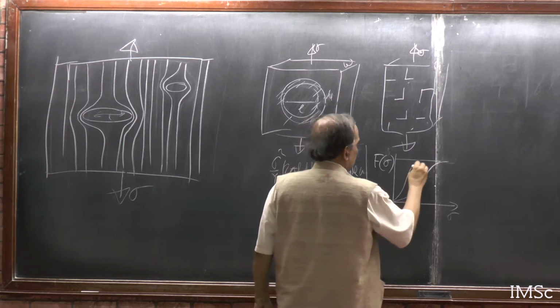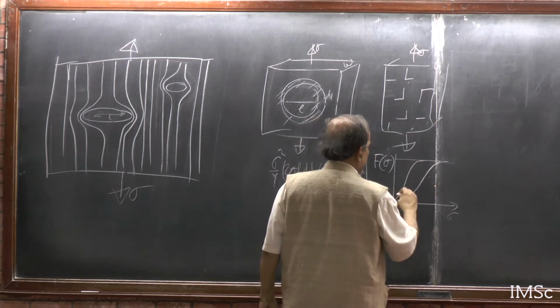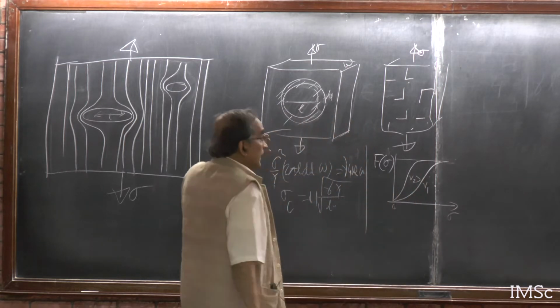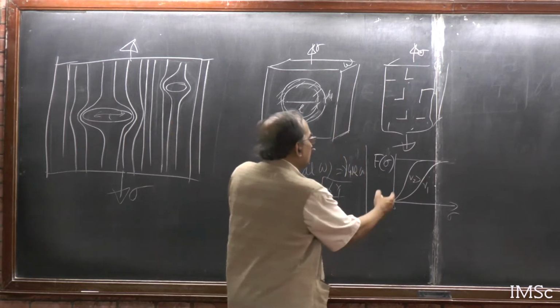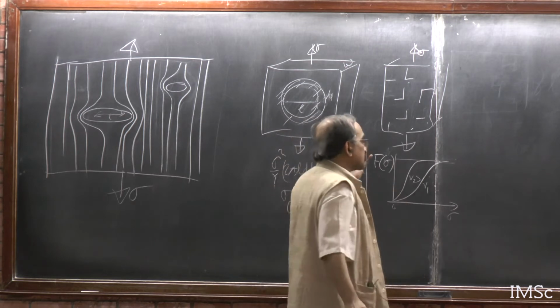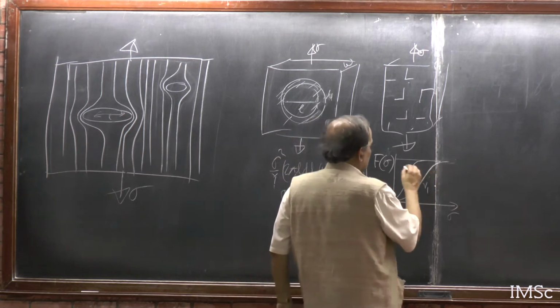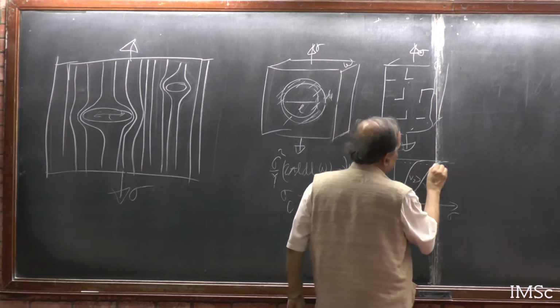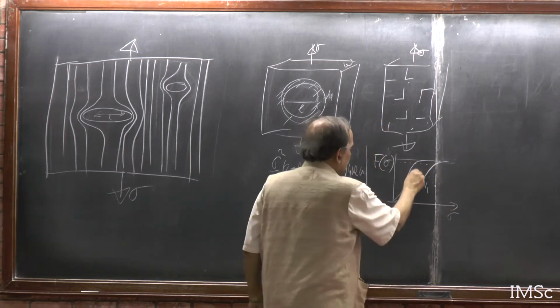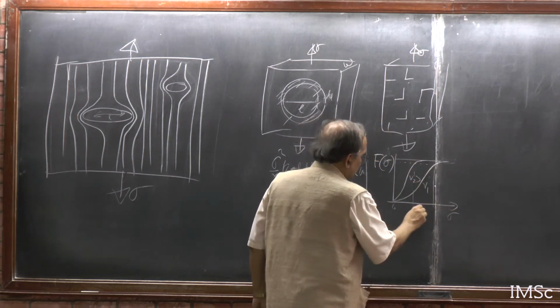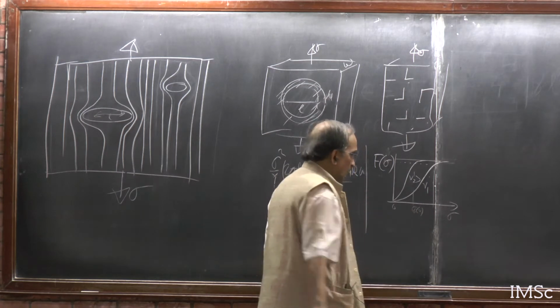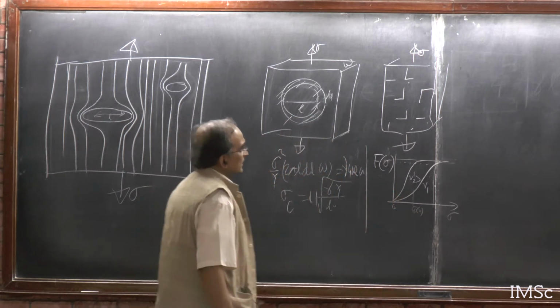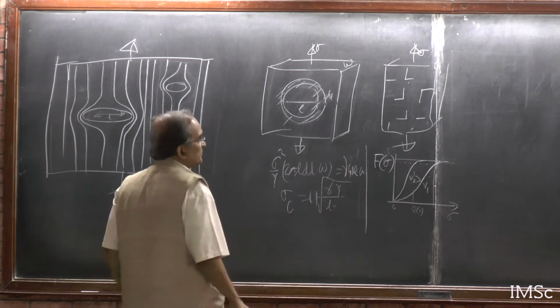For volume bigger one you will get like this, so V1, V2 is greater than this, and so on. Here you cannot talk of a particular failure stress, they would asymptotically touch, but if you say that the failure probability is 90%, then you have a sigma c, but that sigma c is volume dependent, in the sense that as volume decreases, the sigma c decreases.